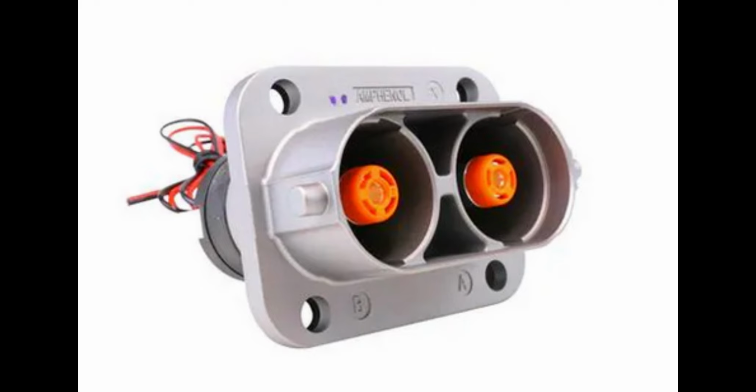So you'll see in the background that there's a red and a black wire. These are attached to an internal mechanism on this panel mount connector. So when you press in the female side of the connector onto these two prongs and fully engage it, it will make a mechanical connection to those two wires, allowing a voltage to flow through them. Now, note this isn't the high voltage that's going to be flowing through it. This is going to be an external connection that we're going to make to the shutdown circuit.